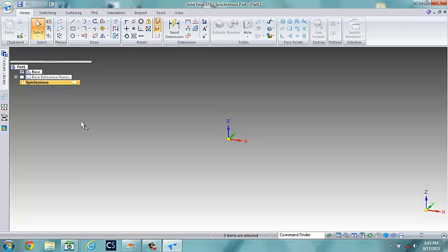This is going to be a synchronous exercise, and if you follow along on page 2-38, it's figure 2-57 and 2-58 that gives us the profile. So what we want to do is draw this profile on the screen, and I'm looking at some overall dimensions, and we'll just kind of block this out. So I've got, first of all, 120 by 10 is going to be the base of this profile, and it'll be on the ZX plane. So what we'll do is select rectangle by corner.